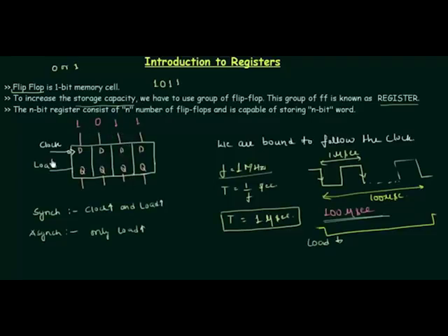And there will be a clear input. You already know what a clear input is. It will reset our flip-flops, and in this case it is going to reset all the values of the 4 flip-flops. This clear is connected inside to all these flip-flops.